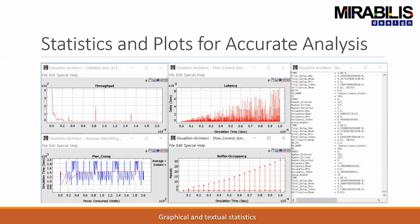By instantaneous, at every point in time, what's going on in all the banks, or what's going on in all the devices in your HBM, and what state they are in. Are they in a refresh state? Are they in active? Are they in standby? Are they in any other state? Or how many pages are open? All of those determine your power consumption at a point. Now, the other aspect is also looking at your average or cumulative power, because that determines how much power you want to get from your battery as well.